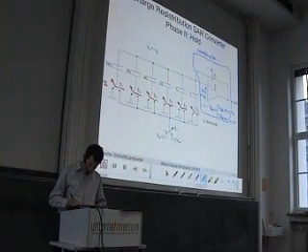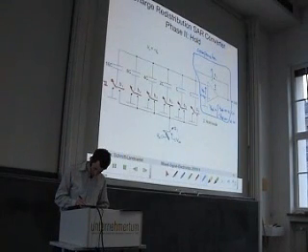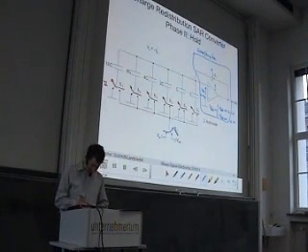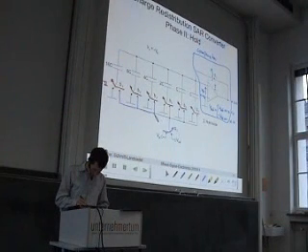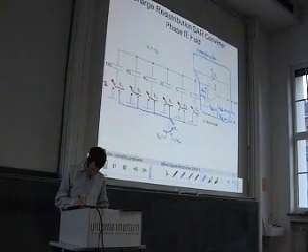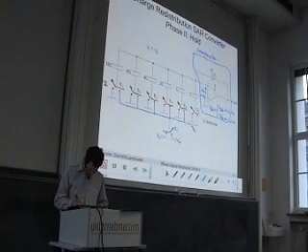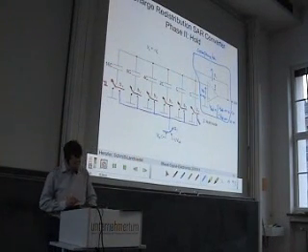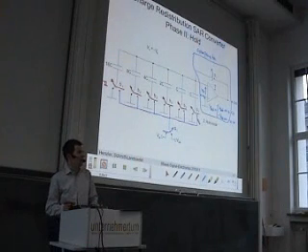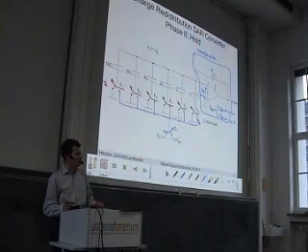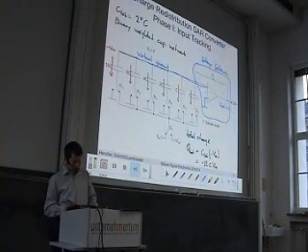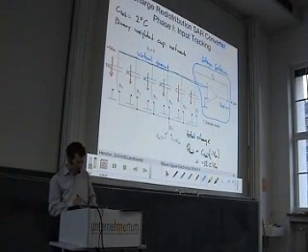And finally, the third step is to switch this switch and connect this rail, which is currently connected to nothing, to the reference voltage. So this is now Vref. What happens to the charge on the capacitors? So on the last slide we had the total charge Q total, which was given by the input voltage and the total capacitance. What happens to this charge?